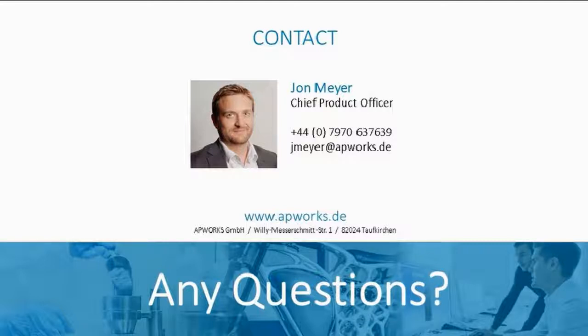And then you're performing fairly standard NDI, dye penetrant inspection, if necessary, X-ray or CT. Generally speaking, the defect that's going to cause you a problem is the surface breaking defect, so one that you can detect with dye penetrant testing. So you're really looking for a crack or a local pore that hasn't been cleaned up in post-processing. In terms of internal defects, the level of internal defects is actually pretty low compared to what you might expect from a casting, for example.